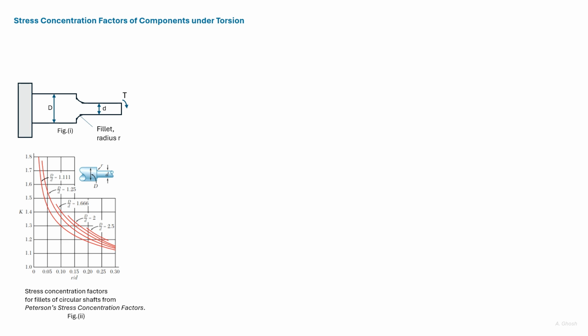The definition of stress concentration factor of components subjected to axial loading or torsion are the same. The stress concentration factor is given as the maximum stress divided by the average stress acting on a component. Thus, we find the average stress and then multiply it by the stress concentration factor to get the maximum stress.